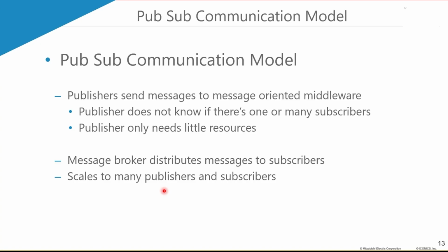So that means that we can use the broker as a firewall or cybersecurity measure as well, because we want to separate the source of data from the client, and we want to limit what we expose to the outside world. Instead of exposing all the data sets or all the data points, we may have a lot of information, but we just want to show only one data point or the total production to the clients. So that's a very good way of doing one-way communication from data source to the client, like a data diode kind of thing and the firewall kind of thing. That's really good, Amanda.